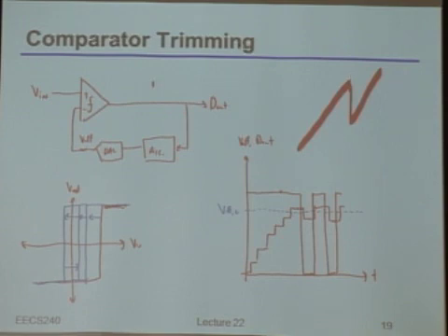you have this feedback loop here, any sort of nonlinearity or badness in that DAC, you can think of it as just being thrown away by the feedback loop. In other words, it's really forcing you to sit on one particular spot in that curve. And then all you care about is exactly how big those residual steps are, because that's really what sets your remaining offset in the whole system.